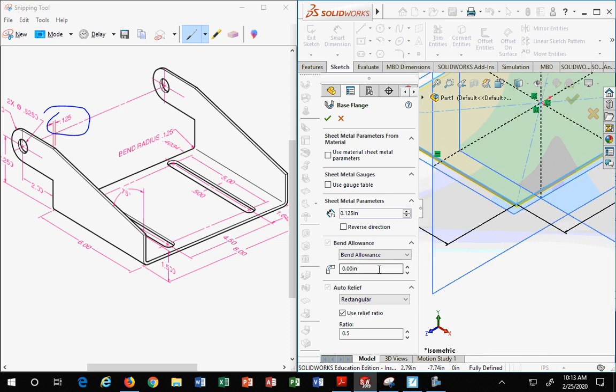Bend allowance, 0 inches. Okay, that's good. I tend to pick K-factor. Okay, K-factor is a standard rule of thumb we use in the field when we're sheet metal bending. Half the material thickness, 0.5, is your bend allowance, is a typical term. Otherwise, you break the material, okay, or you stretch it. Depends on what happens. You either rip it or it'll stretch, okay. Typically, that K-factor is allowing for a gentle bend. You can draw die a bend, but that's another conversation.